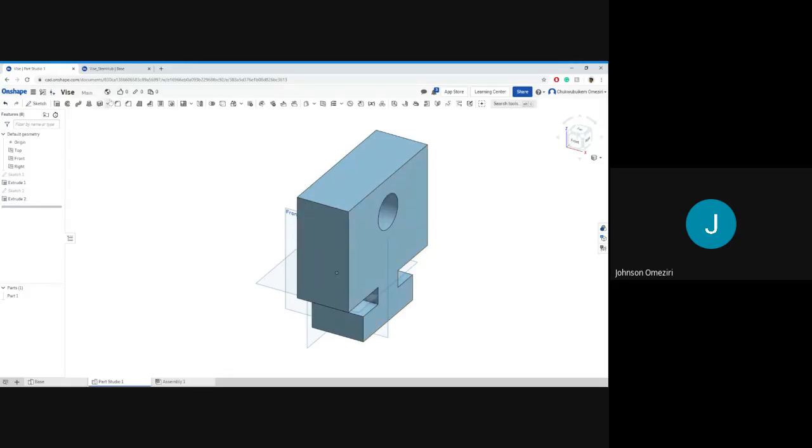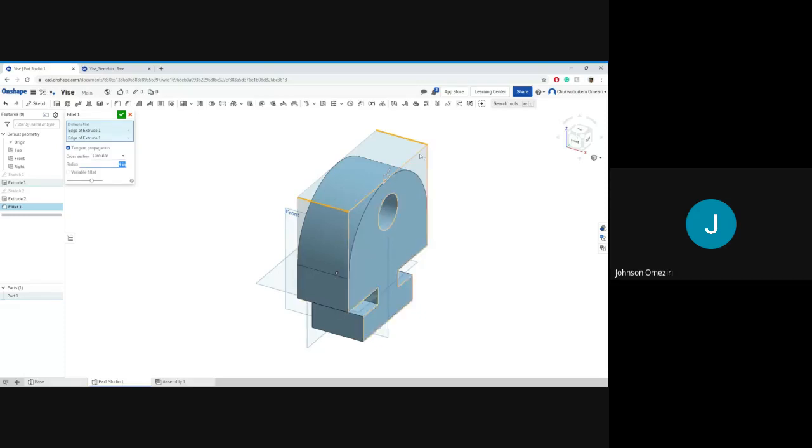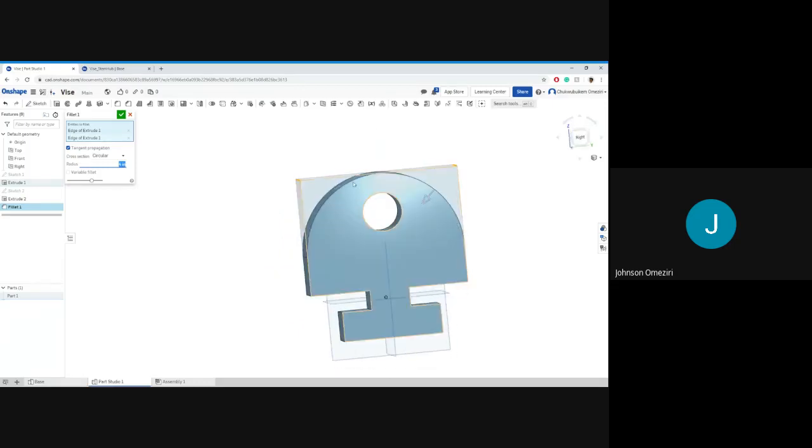I want to click on this fillet icon here, fillet, or Shift F. So I'll press Shift F. That shows up. Now I need to choose where I want to fillet, what side I want to make round. So I click on that edge first. I click on this edge. Then I change this to 4. You see, now that automatically rounds out the feature because the size of this shape was 8. If I make one side a radius of 4 and the other side a radius of 4, it makes it round like a semicircle. Then I click OK once this is done.